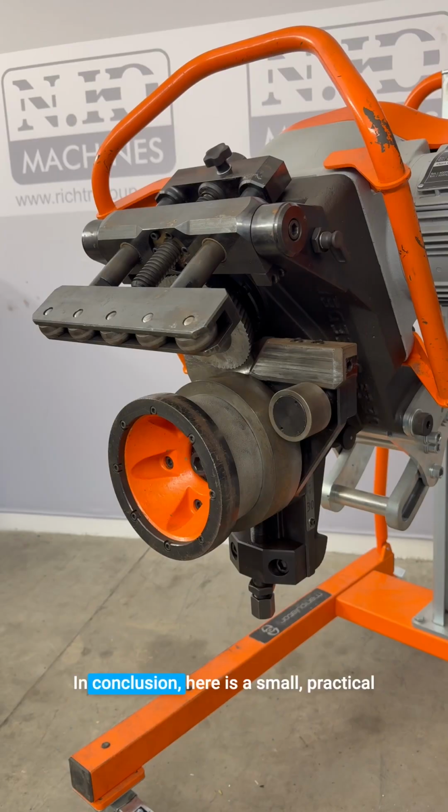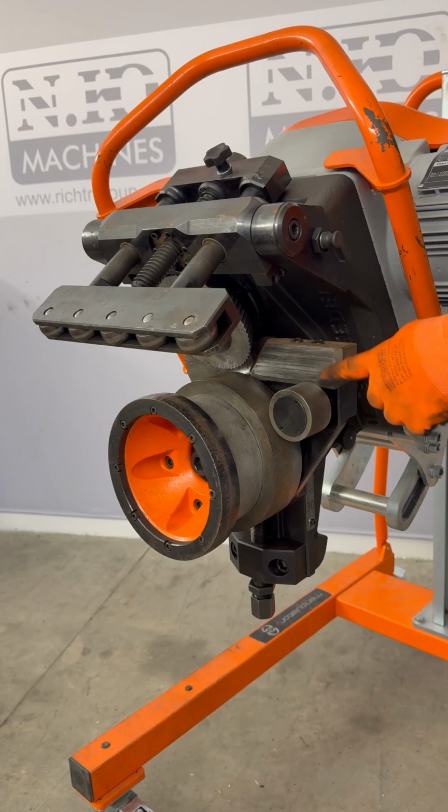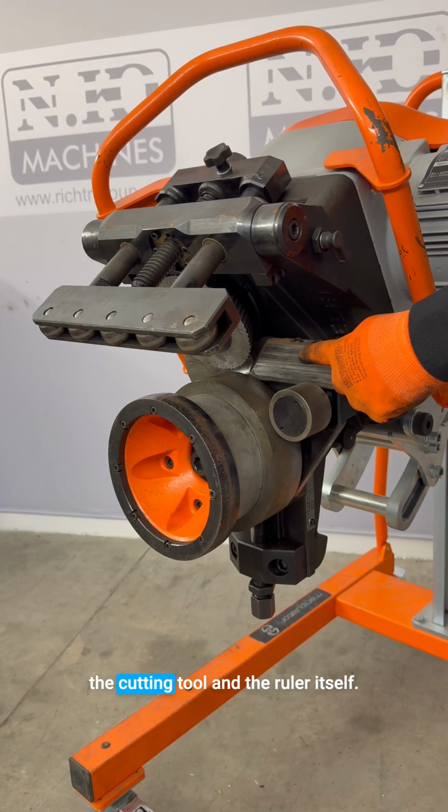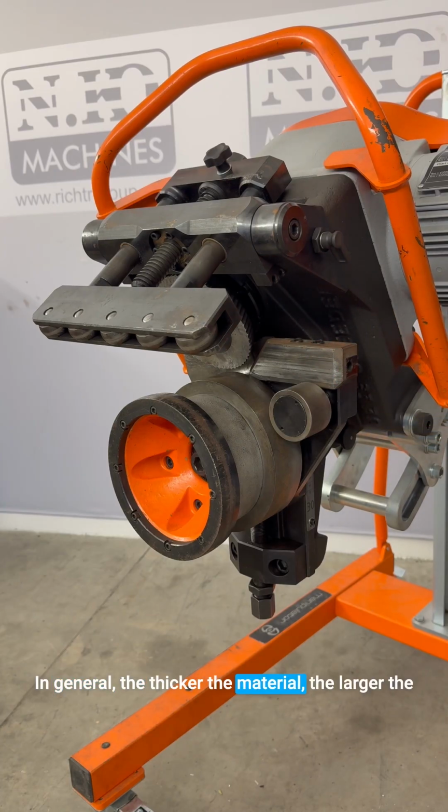In conclusion, here is a small practical tip for the more demanding user. The input guide ruler has two positions that adjust the distance between the cutting tool and the ruler itself. In general, the thicker the material, the larger the gap between the tool and the ruler.